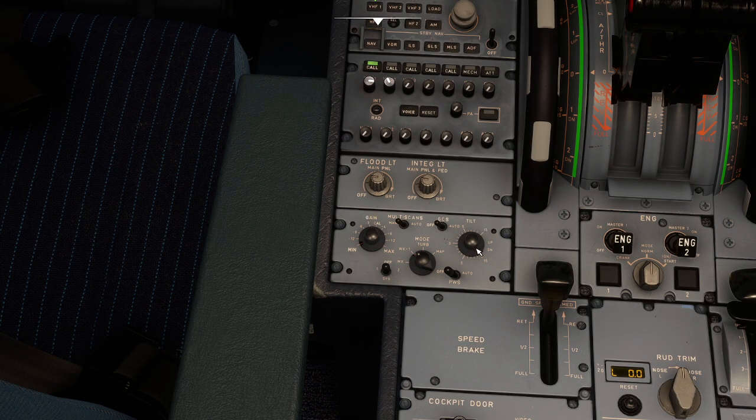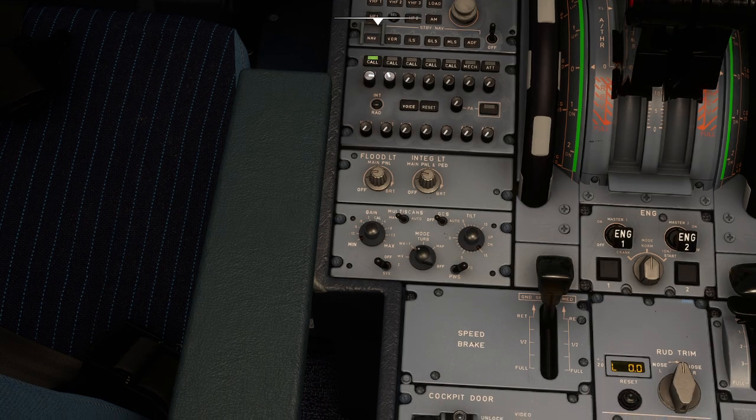And then after that I'm coming over here. This is my weather panel. I think the weather panel is already configured to WXR. This is the only thing configured in my aircraft, and I can also put this to auto, and I can also make the SYS to 1 or 2. I'll make it 1 because this is my pilot side 1.